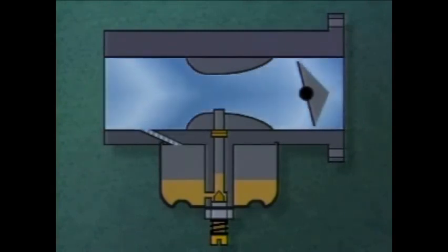As the throttle plate closes and we lose the pressure difference between the venturi and the atmospheric pressure on the gasoline in the bowl, we gain some significant pressure differences in some other areas of the carburetor. One place where we gain a significant difference in pressure is between the engine side and the venturi side of the throttle plate. As the throttle plate begins to close, the air moving past the throttle plate increases in velocity, trying to get into the engine in an attempt to fill the void created as the piston moves down the cylinder bore. Remember Bernoulli's principle.